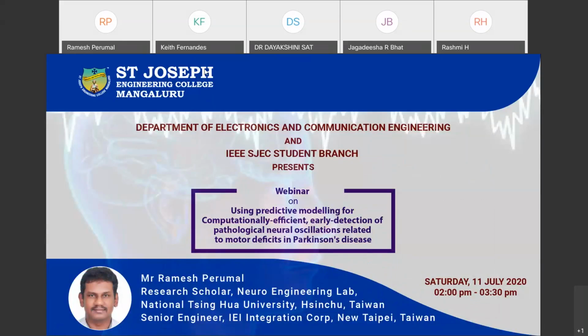Hello, Dr. Udupi Niranjan. The golden truth can be generated by using the Hilbert-Huang transform. Compared to the wavelet transform, of course, we can also determine the time frequency. We can use the continuous wavelet transform to generate the time-frequency distribution. But I already mentioned, even though we have good resolution, the wavelet shape is still crucial. So I used the Hilbert-Huang transform to compute the ground truth.